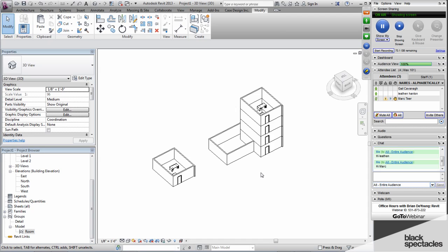For example, if we had an architectural model and we were doing all of the documentation in that model, and then the structural engineer linked that model into their model, it took on average about 30% longer to do certain things if that model contained sheets than if they linked in a building model that contained no sheets whatsoever and just three-dimensional geometry.